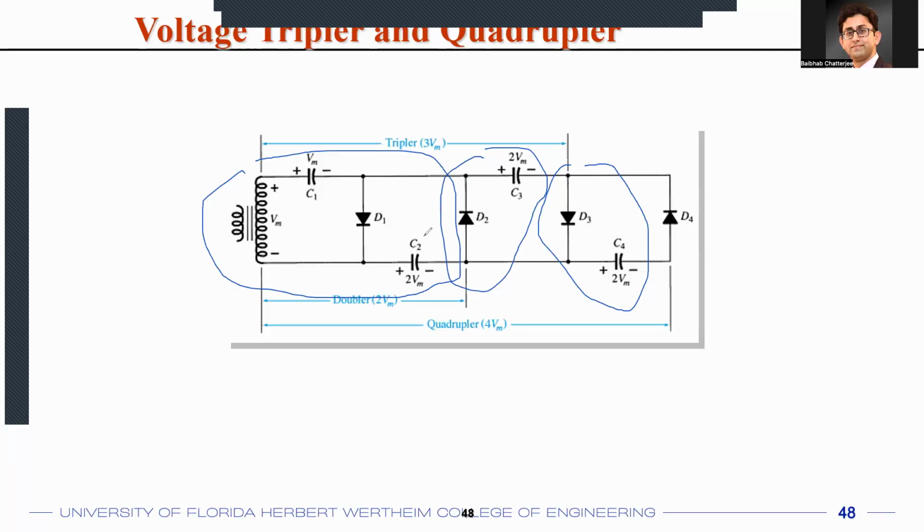So of course, if you are starting with just 1 volt, right? Or maybe 1 volt or 2 volts, then you have a diode drop of 0.7 volt. So what you're going to double is basically the voltage that is left after having the diode drop. So having more and more diodes becomes not that interesting after a few stages. If you start with a very high voltage, then yeah, you can still continue doing it. But then the diode has to withstand that very high voltage and still have a very low threshold voltage, which does not happen in reality.